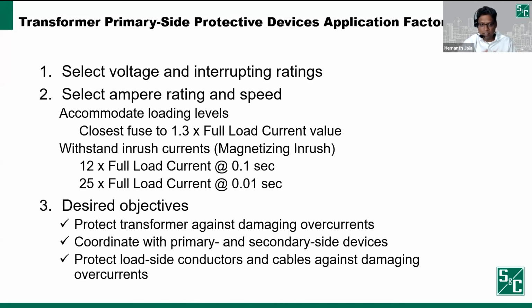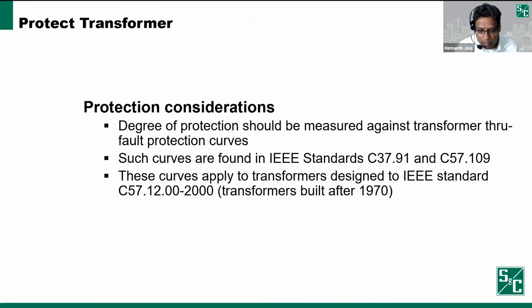And again, I'm listing the design objectives of picking a fuse. You want to protect the transformer against any damaging overcurrents, and you want to make sure that you coordinate with the primary and secondary side devices. You also want to protect the load side conductors and any cables on the system from any damaging overcurrents. I talked a little bit about the transformer and how to protect it.